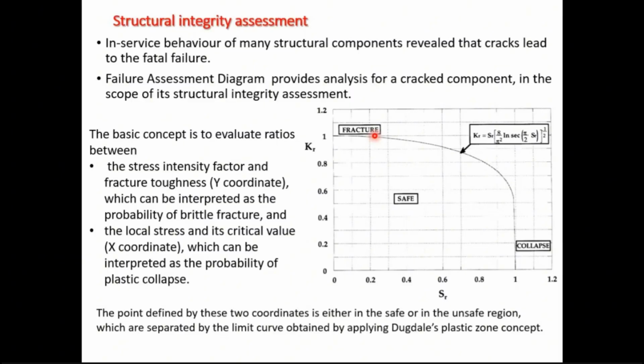We did that in two cases. One is not so conservative, when we took into account the real dimensions of the crack. The other one is if we assume that the crack goes all the way through the circumference, so that would be the more conservative one.